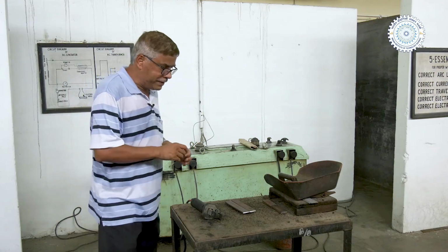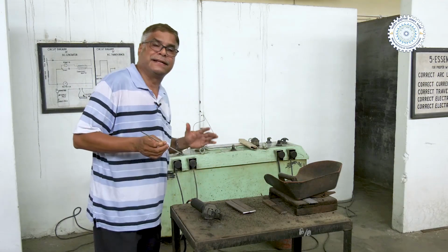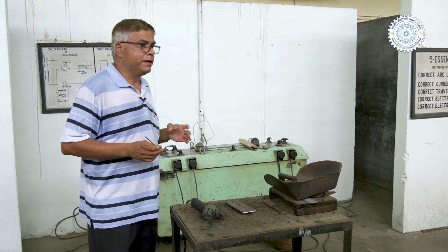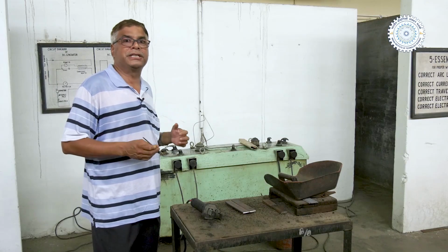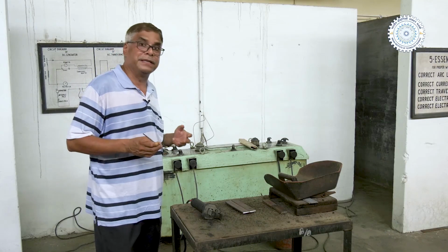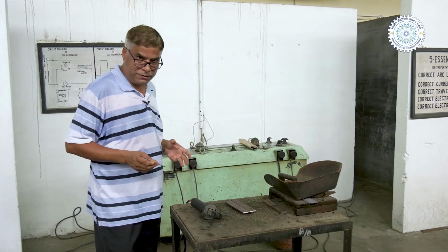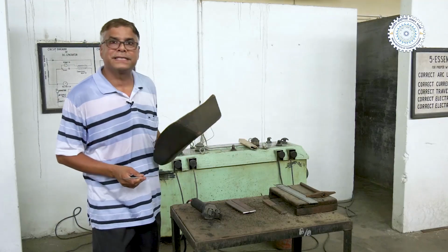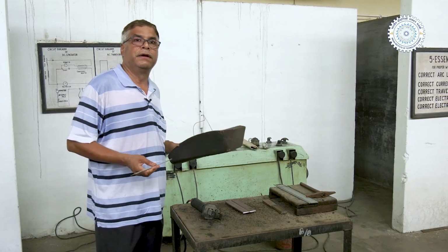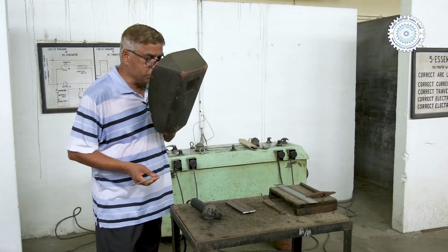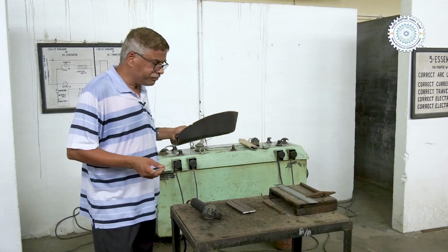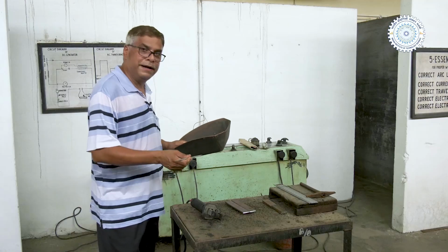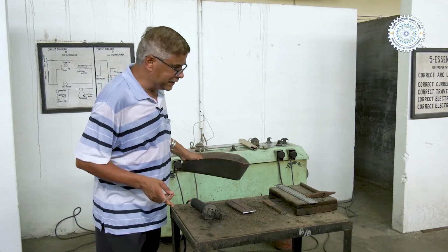So, during the welding very intense heat is generated, and a lot of harmful radiations are also generated during arc welding. So, it is very important to protect the eyes. For protecting the eyes, a face shield of this kind can be used, or goggles are also there for the protection purpose, so that you can easily handle the arc as well as control the arc and the weld pool as per the need.